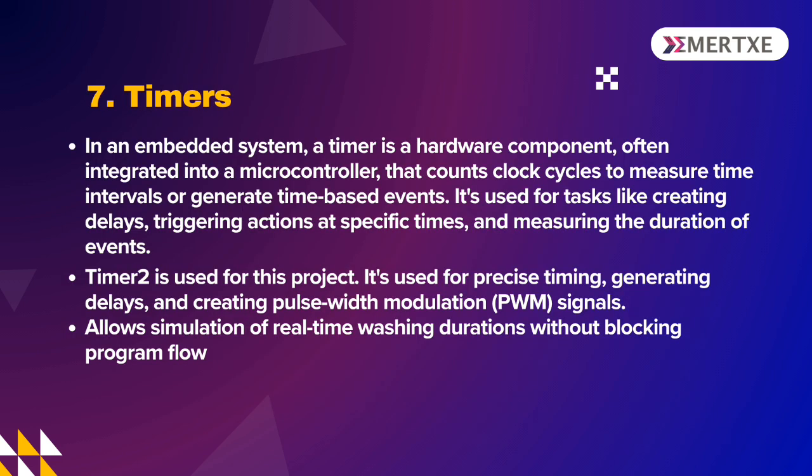And the last thing is timers. In an embedded system, a timer is a hardware component, often integrated into a microcontroller, that counts clock cycles to measure time intervals or generate time-based events. It is used for tasks like creating delays, triggering actions at specific times, and measuring the duration of events.